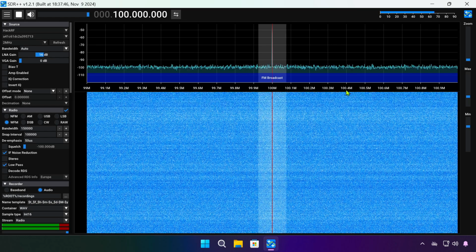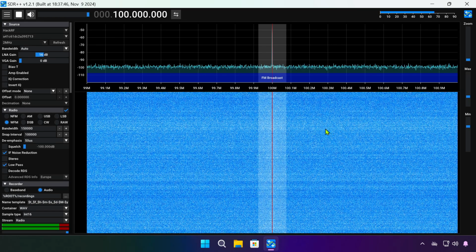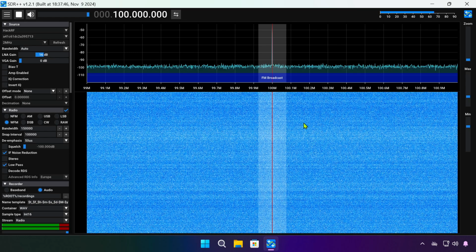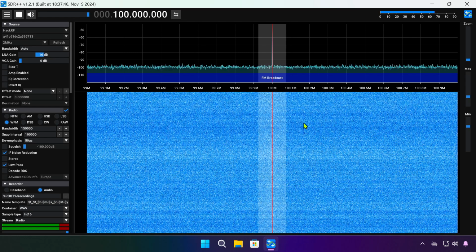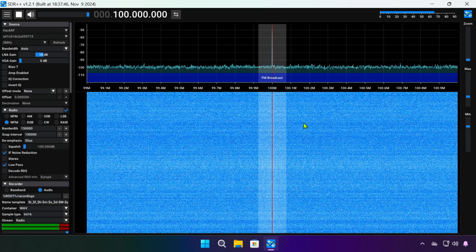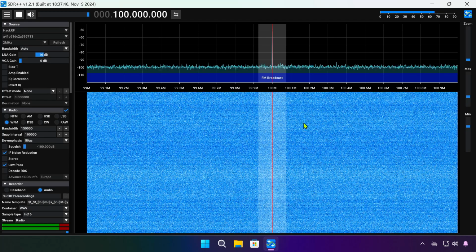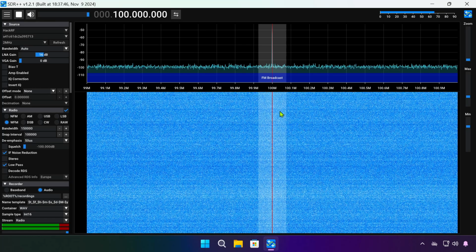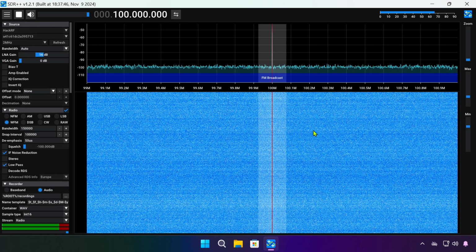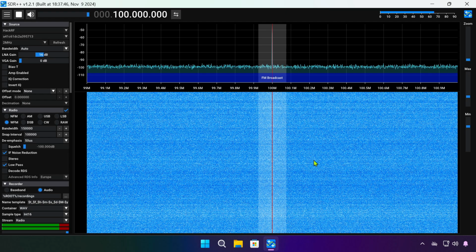Depending on your SDR receiver, you might have several AGC settings. For example, fixed levels: devices like the Airspy HF+ Discovery provide preset automatic gain control levels, off, low, high, like that, allowing you to select how aggressively the receiver balances signal levels.